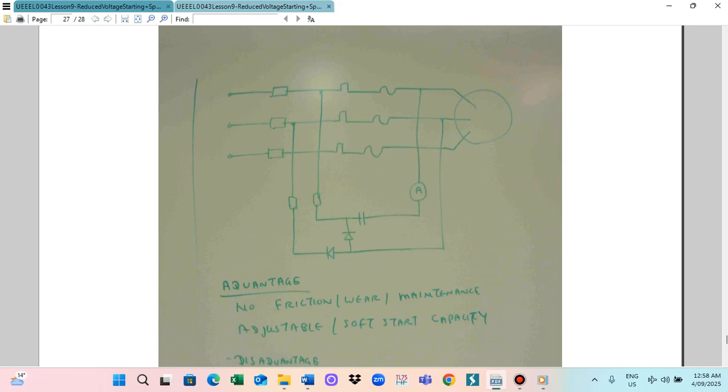So this connector was a very loose connection. Normally we open the controller block and check everything, but it was a very loose connection like this, so we could see it by eye. Finally we tested it and found this very loose connection. So we had to rejoin this wire, and then we ran the motor correctly.